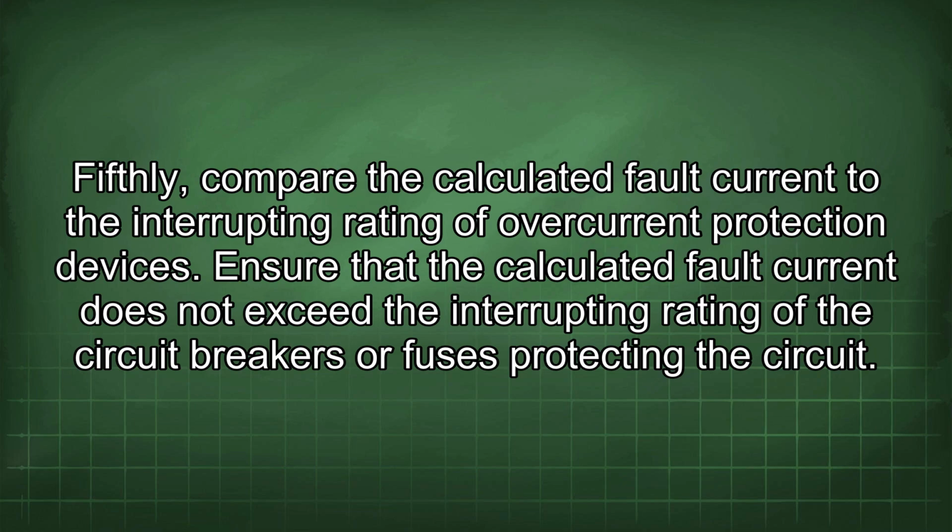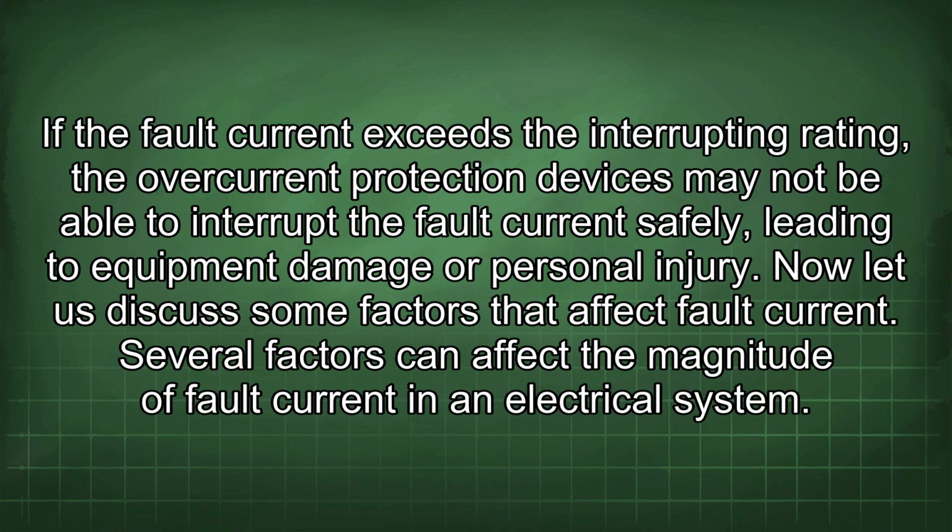Fifthly, compare the calculated fault current to the interrupting rating of overcurrent protection devices. Ensure that the calculated fault current does not exceed the interrupting rating of the circuit breakers or fuses protecting the circuit. If the fault current exceeds the interrupting rating, the overcurrent protection devices may not be able to interrupt the fault current safely, leading to equipment damage or personal injury.